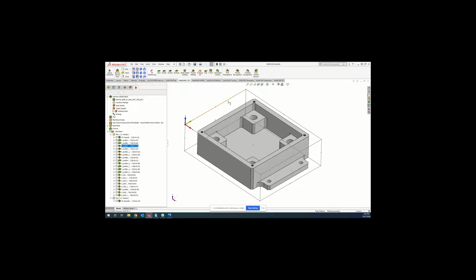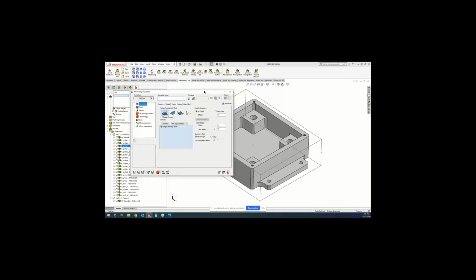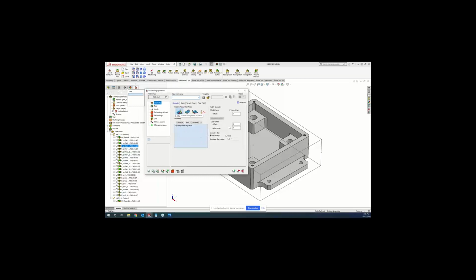I'm going to go ahead and open up an iMachining operation and just backtrack a little bit to what we've talked about the last 2 weeks. Our first one is all based off of feature recognition by faces. If you're looking to machine a specific area, all you have to do is click on that face. It can be the top face, and it can be multiple faces. But in certain scenarios, if there's overlapping geometry in there, sometimes it will not get all the faces. So very simple, easy to use.